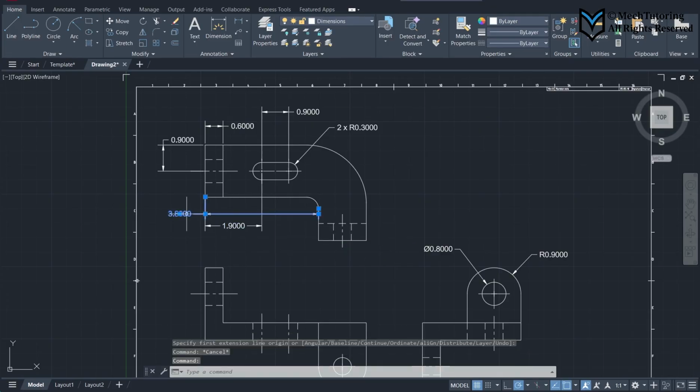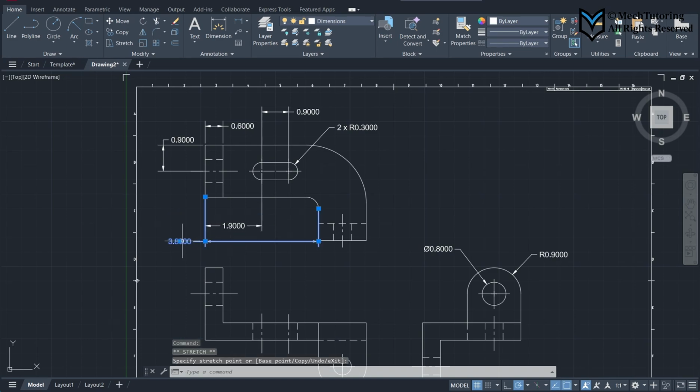And let's move this dimension because it's a bigger dimension. Move it away. Look, when you move it, you have to be really careful. Don't drag it, just click on the screen and move it, okay? And I'm gonna move it even further because otherwise it's gonna create an illusion that it's connected to that line, okay? So that's done. You can move it inside if you want.